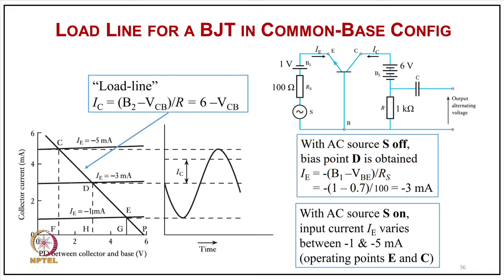So, that is the way you will be getting it on this characteristic of this load line, and you will certainly get the output voltage which will be of this shape, because you will get an AC voltage with a DC offset, but the DC offset will go out because of the capacitor. So, you will get an AC voltage output here which is amplified corresponding to the gain of this voltage. So, you have this small voltage, and you get a reflected amplified voltage in the output.